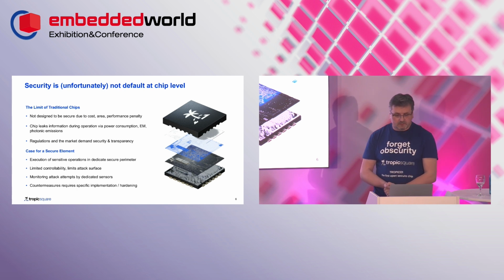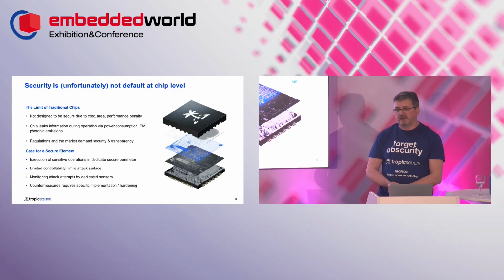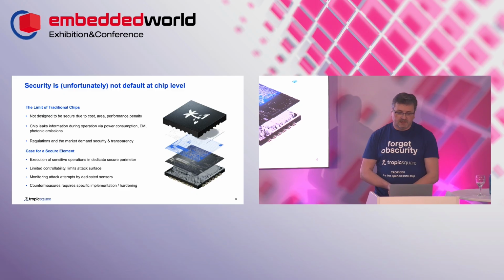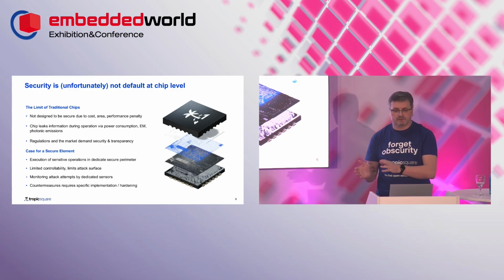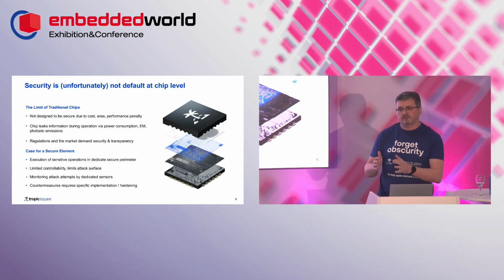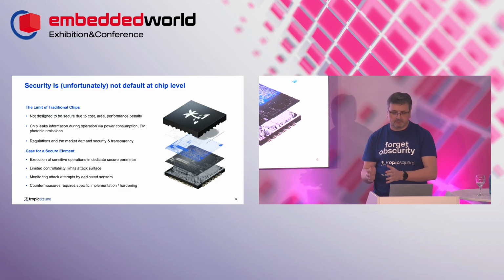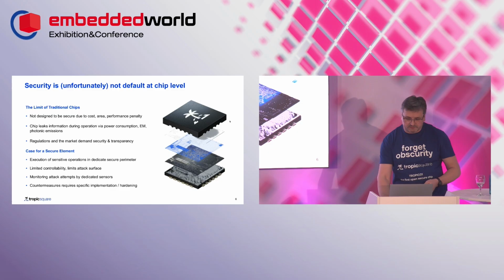Countermeasures also require specific implementation hardening, which might be difficult to implement in regular logic. And in reality, this may also have an impact on the technology node you choose for your ASICs. And to be really flexible, we decided to build this secure element as a standalone device, which can be connected to any microcontroller or device which has to be secured.